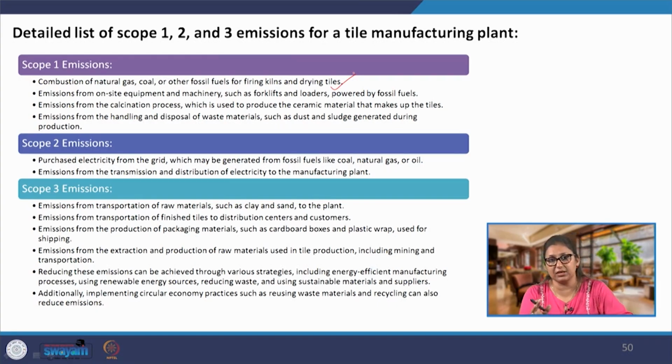So, in India when we get the emission factor, what we normally do, sometimes we can only apply the emission factor to the number of units consumed at the facility itself, and then add T&D losses separately, or we can multiply by a factor to take into account the T&D losses and then multiply by the emission factor to get the total emissions due to the electricity from the generation point to the consumption in our facility. So, both of these will be part of scope 2 emissions.